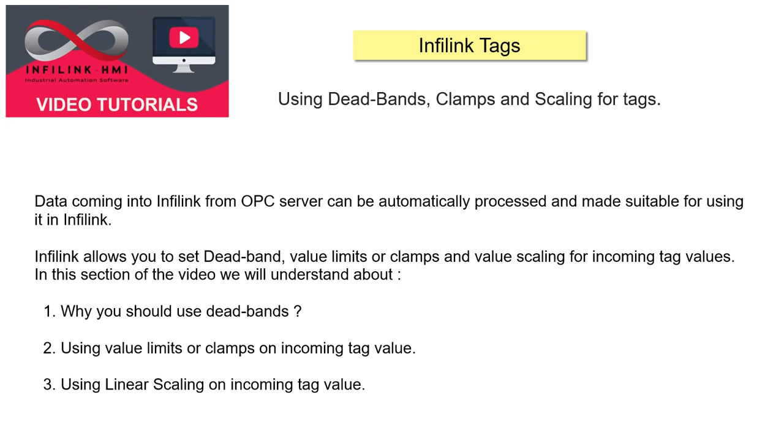Data coming into Infilink from OPC server can be automatically processed and made suitable for using it in Infilink. Infilink allows you to set deadband, value limits or clamps, and value scaling for incoming tag values. In this section of the video, we will understand why you should use deadbands, using value limits or clamps on incoming tag value, and using linear scaling on incoming tag value.